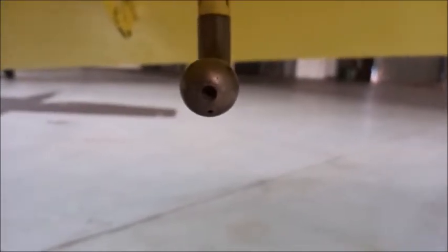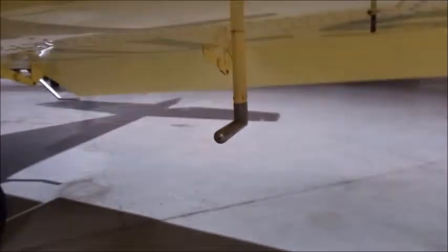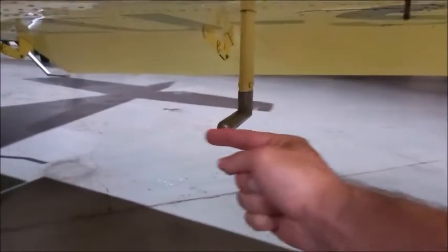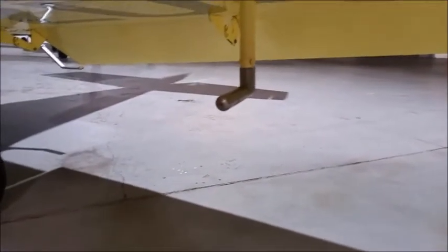Okay, then we come here to the Venturi tube. We've got to have a look at the inside of the Venturi tube and make sure that there's nothing inside of it. You could have an insect, like a wasp, that created a nest over there. The purpose of the Venturi tube is to detect airspeed. Essentially it's the airflow going into this tube. It's a pressure sensor, and depending on the amount of air flowing into it because the aircraft is moving forward, it will tell you what the airspeed is, detecting it in terms of the air pressure.